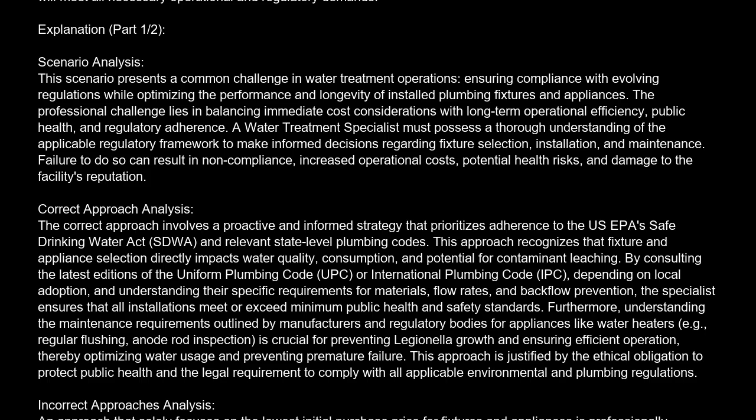Furthermore, understanding the maintenance requirements outlined by manufacturers and regulatory bodies for appliances like water heaters, e.g., regular flushing, anode rod inspection, is crucial for preventing Legionella growth and ensuring efficient operation, thereby optimizing water usage and preventing premature failure. This approach is justified by the ethical obligation to protect public health and the legal requirement to comply with all applicable environmental and plumbing regulations.